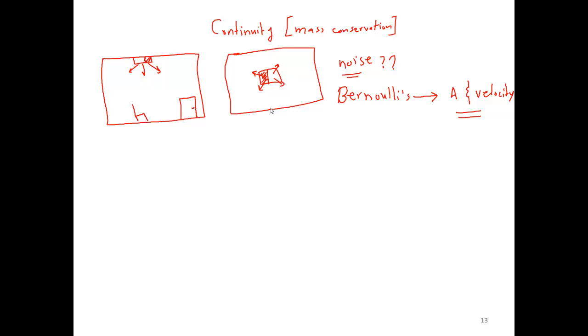So I just wanted to go over this example. Also, another thing: if the door was closed and we put more CFM into the room, what would happen, for example? Or if we close the door and then we seal this very small gap here, and all windows are sealed, and then people complain that they're feeling hotter inside the room. Why?